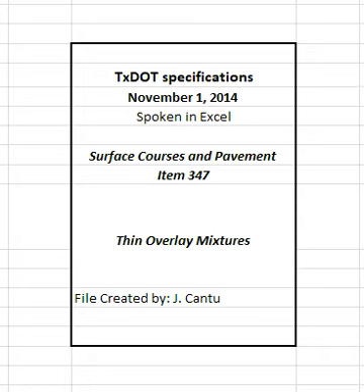Take immediate corrective action if the VMA value for any sublot is less than the minimum VMA requirement for production listed in Table 6. Suspend production and shipment of the mixture if the engineer's VMA results on 2 consecutive sublots are below the minimum VMA requirement for production listed in Table 6. Suspend production and shipment of the mixture if the engineer's VMA result is more than 0.5% below the minimum VMA requirement for production listed in Table 6. In addition to suspending production, the engineer may require removal and replacement or may allow the sublot to be left in place without payment.